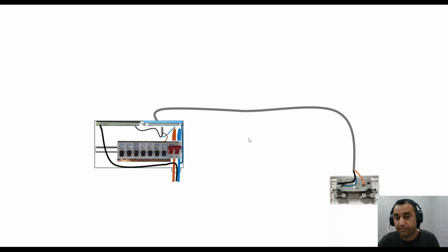If 25 amps is going through this MCB, it might take about 1 minute, a couple of minutes before it triggers. If it's 30 amps, it might take half a minute to trip. And with a type B MCB, it takes about 5 times its rating, so if it's 20 amp, it takes about 100 amps to trigger instantly. It will trigger within the required time, which is 0.4 second because it's a TN-S system. In a TN-S system, we have to achieve a 0.4 second tripping time.